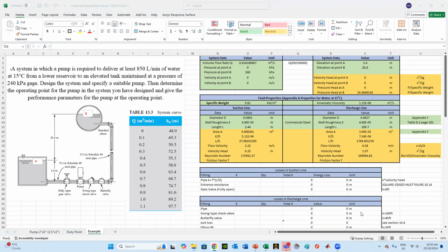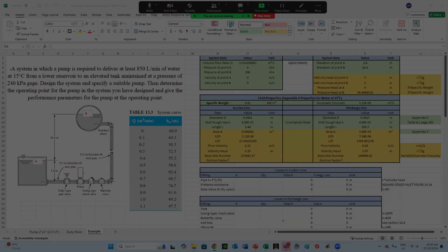Now, from the same chapter 8, there are two methods to get the friction factor. One is you get it straightforward using the Moody chart or Moody calculator. But also, as I told you, the chapter provides you with an equation, easy and ready to use, which I will just copy. I'm just trying to get it from the textbook, the friction factor for turbulence. So I will print screen that equation.